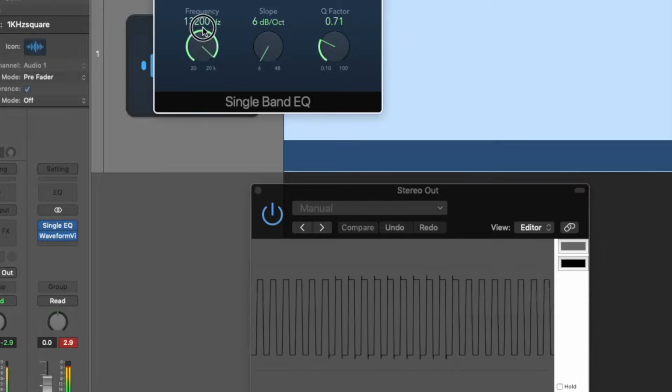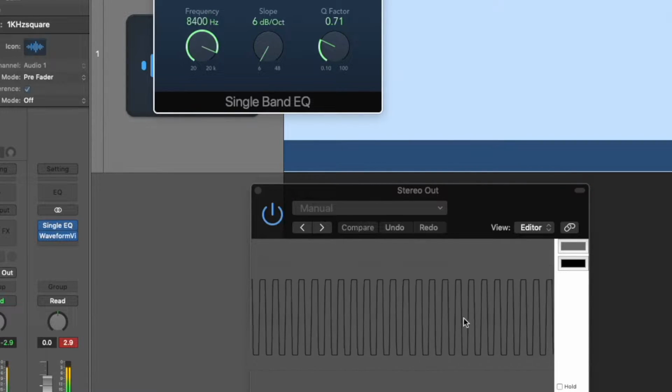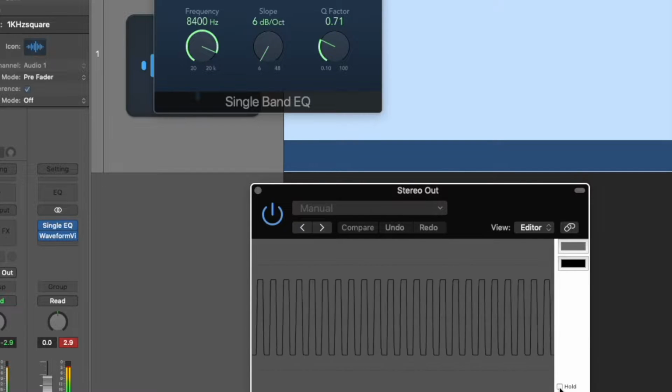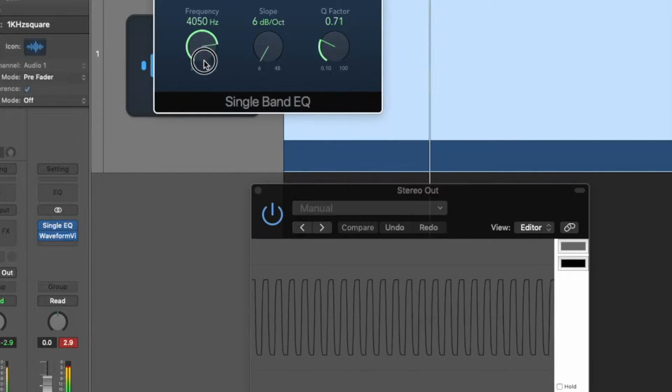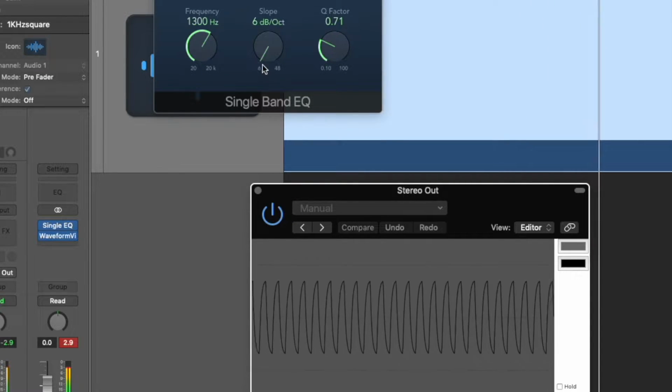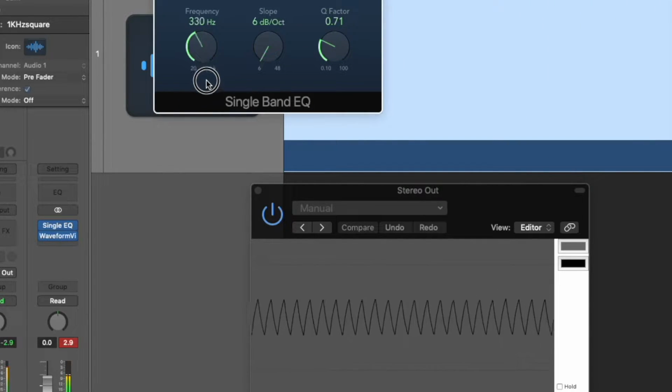So what I'm going to do is sweep the -3 dB point closer and closer to the fundamental, thus attenuating the upper harmonics. And as we see, the waveform changes. As we start up over around the 8th, 9th, 10th harmonic, the wave looks pretty square.